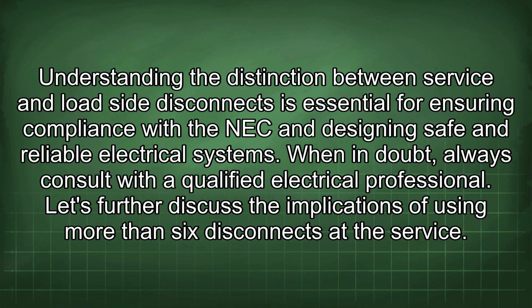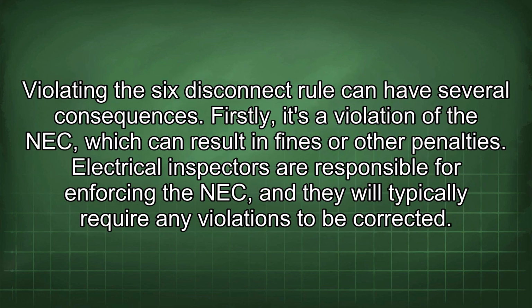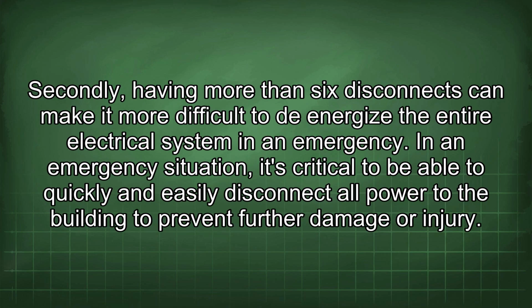Let's further discuss the implications of using more than 6 disconnects at the service. Violating the 6 disconnect rule can have several consequences. Firstly, it's a violation of the NEC, which can result in fines or other penalties. Electrical inspectors are responsible for enforcing the NEC, and they will typically require any violations to be corrected. Secondly, having more than 6 disconnects can make it more difficult to de-energize the entire electrical system in an emergency. In an emergency situation, it's critical to be able to quickly and easily disconnect all power to the building to prevent further damage or injury.